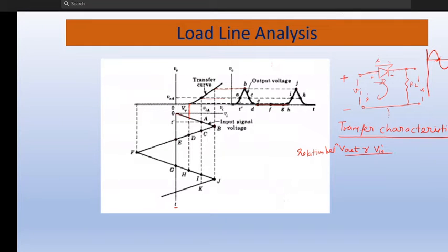I just ask you one thing, anybody can try in Multisim and then answer. If I say that in reverse bias no current will flow, but if you look practically, there will be a little. Some micro amps of current will be there. Now if you increase the frequency, if this signal is of higher frequency, you will find that there will be some small current. This portion will not be clipped properly.